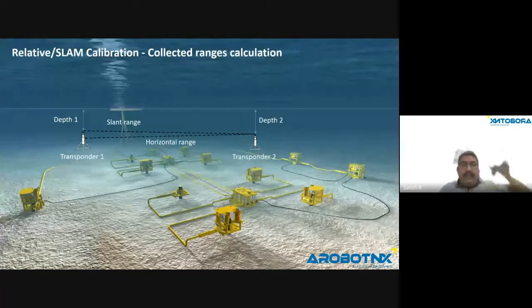And these things, when we had training, they told us every time, so that becomes a habit for us that we have to remember this whenever you put it down. So before the LBL transponder goes off deck, make sure you measure the offsets, the height, and also make sure where the depth sensor on the transponder is. So make sure that is also measured with respect to the height. Definitely OEMs have got that in the spec, I'm 200% sure. But as a practice, make sure you have all those measurements with you before the transponder goes off deck.